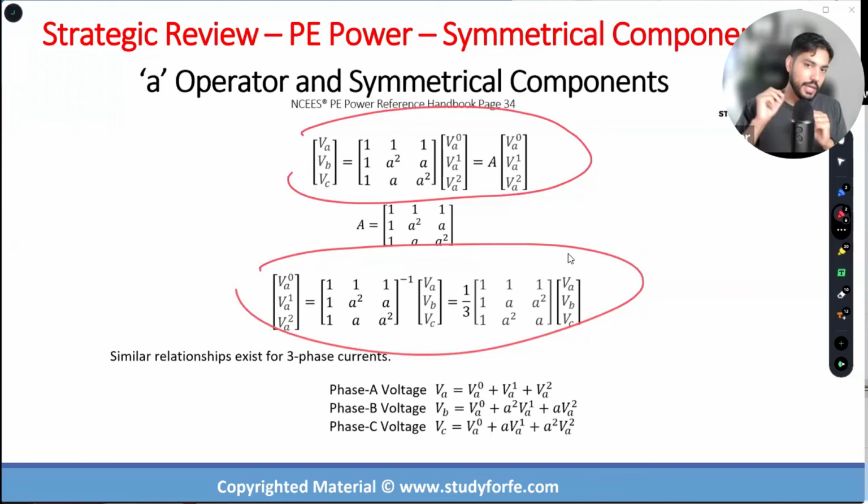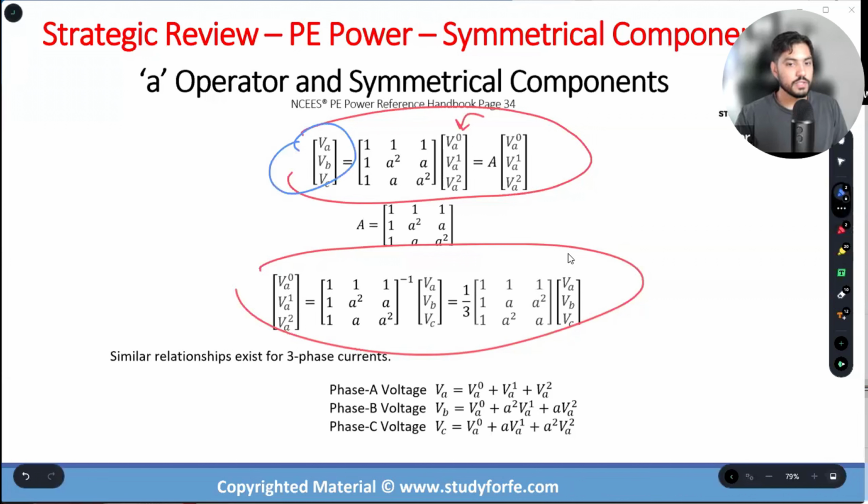The real application piece of symmetrical components is going to show up a little bit later in section number 4 when we are dealing with fault analysis. And that's where you are going to start using this as prerequisite information. So if I give you a system that contains the symmetrical components and I'm asking you for phasor quantities, right? You're going to use this first matrix. If I give you the phase quantities and ask you for the symmetrical components, you're going to use this matrix. And the matrix is pretty simple.